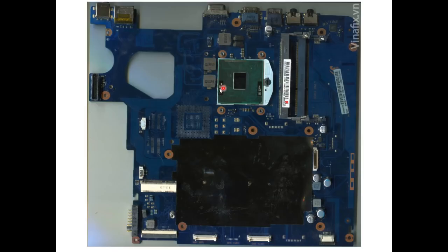These are the CPU core and these are the graphics core. Suppose this voltage is not coming, and you can check on the DC power supply also. If the DC power supply current is something like 150 milliampere or 250 milliampere, in between 150 and 250 milliampere, then your CPU core voltage is not generating.